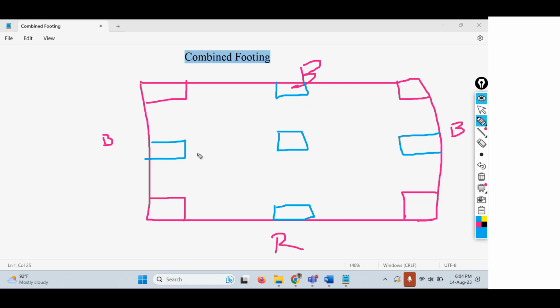Now, in some cases there are situations where the requirement of load transfer will be in this way. Suppose you have arranged the columns in this way, so there are a total of 9 columns available in this site. Now you need to provide one extra column along with its footing somewhere in this portion. Assume that all the 9 columns, excluding this one, have isolated footings.